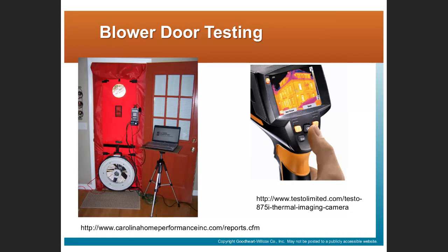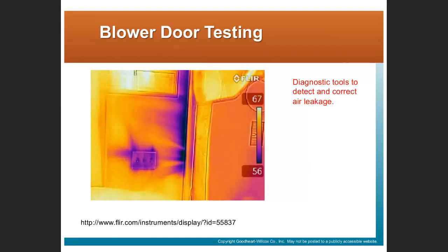Right? Years ago, Francis and I had someone come in and insulate our home, and at the end of the job, they did a blower door test, and they could tell how much tighter they had made, how much they had improved the air tightness of our home by virtue of the work they did with insulation and air sealing. Right.